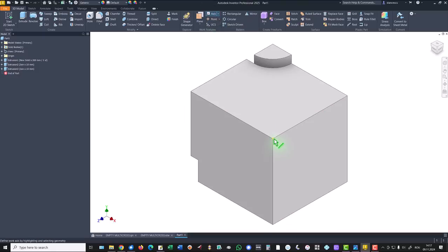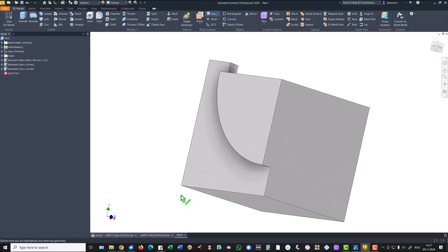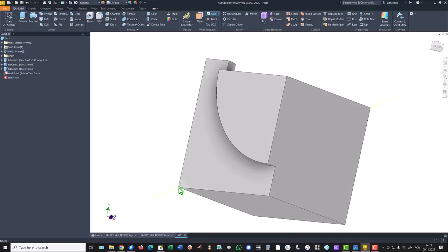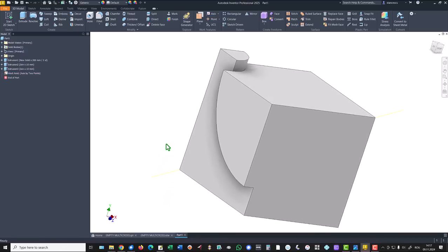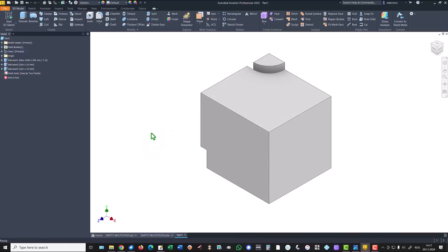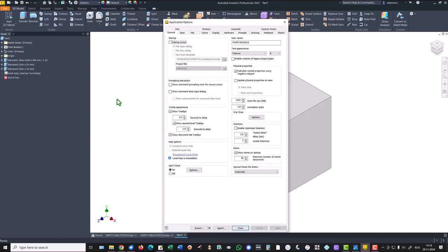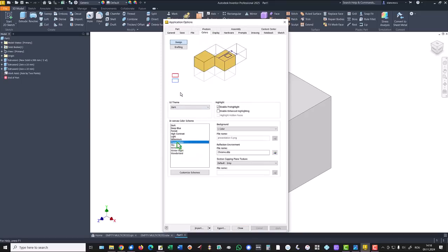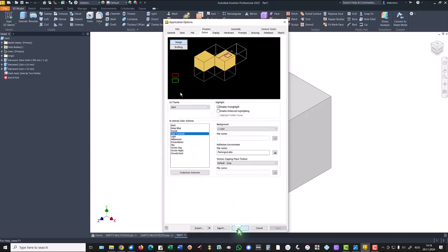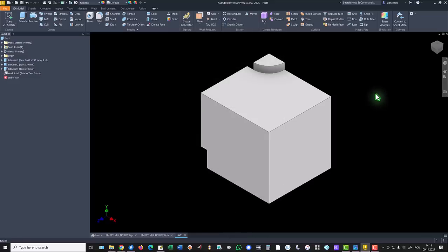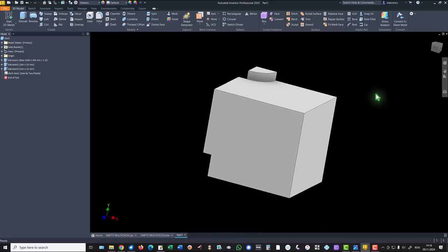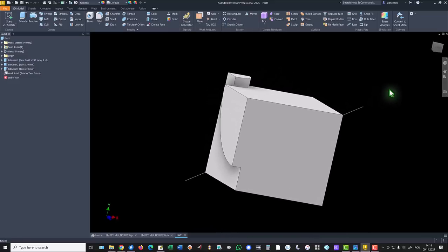We continue by creating an axis based on this point and going to the other opposite corner. Now we have that axis, but we don't see it. To see it, we use the sequence Alt F I and selecting colors, high contrast, OK. Now we see it.